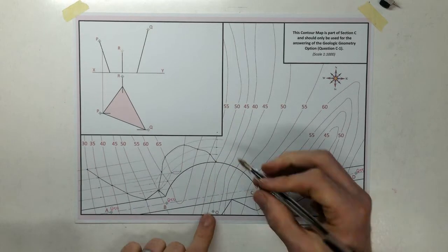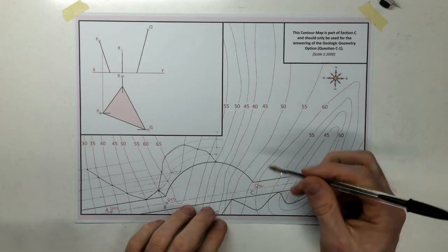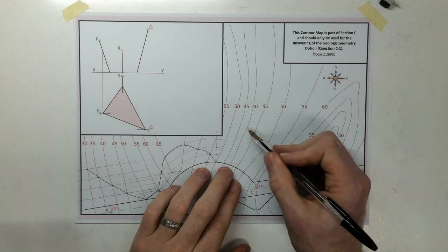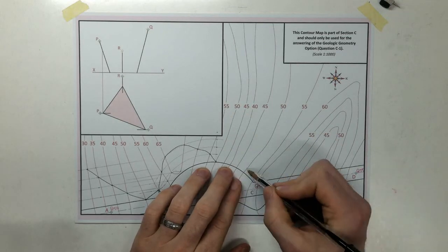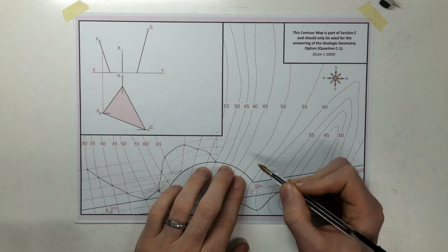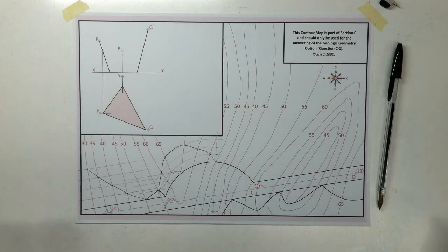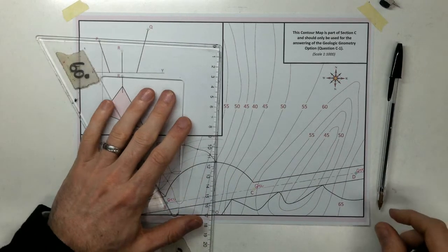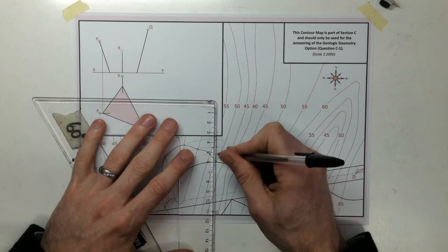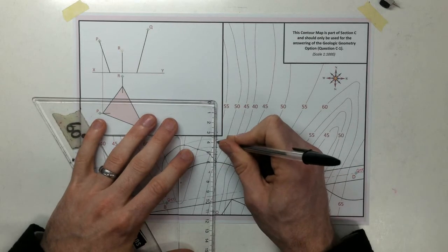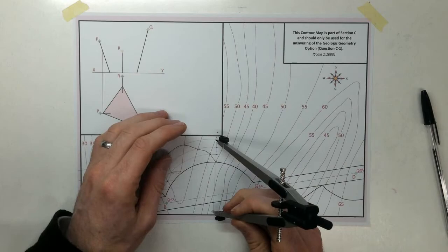All right. Now, next we are continuing on along our curve. Our heights there are at a lower height. So from this 50 to this 50, we'll be doing a fill. So we're back to our 10 intervals, so I can measure 10 off each of these. 10, 10, 10. I'm using O as my center.